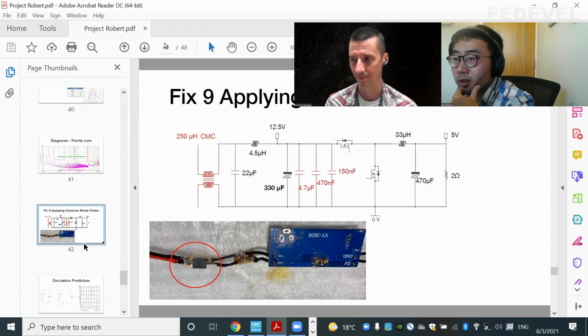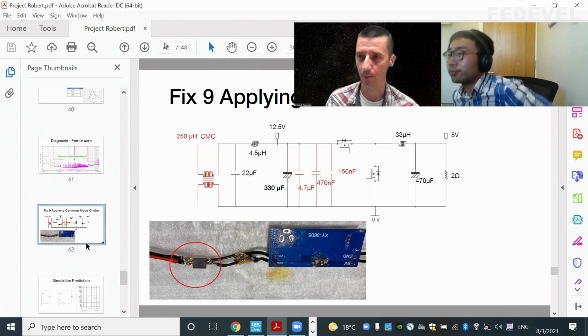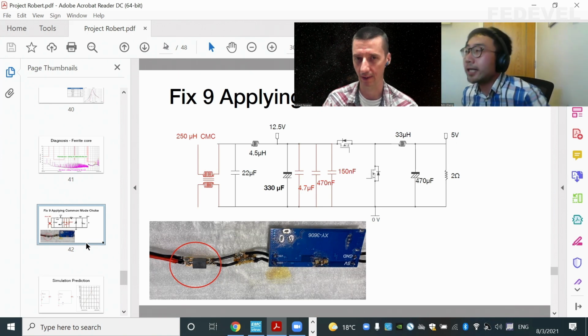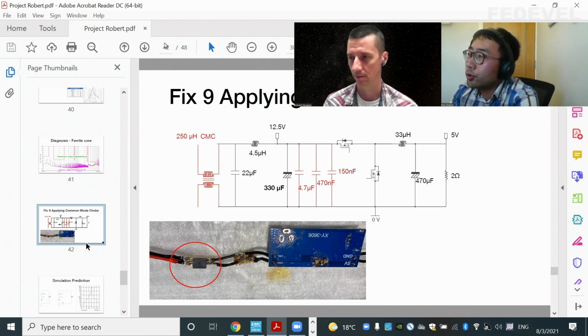So we used the ferrite just to prove that we have a problem with this common mode noise, and we need to filter it. That's why often, if you send a sample to a test house, the test engineers will put some ferrite core on the cable, and then if they see, say, 10 or 20 dB reduction, they will tell you, look, you need to do something on your common mode filtering. Then as an engineer yourself, you might go back and say, how can I improve it? Shall I put a common mode choke, or shall I use something else? There are many ways of doing it.